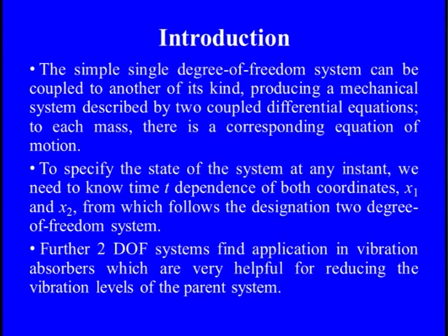In today's lecture we are going to discuss free and forced vibrations on the 2 degrees of freedom system. As we discussed for the single degree of freedom system, it can easily be changed into 2 degrees of freedom by simply coupling a similar kind of structure to another. In that way we can produce the same mechanical system, which can describe 2 coupled differential equations, since it is a discrete system. So we have ordinary differential equations, and we can form 2 equations which represent the 2 degrees of freedom system.